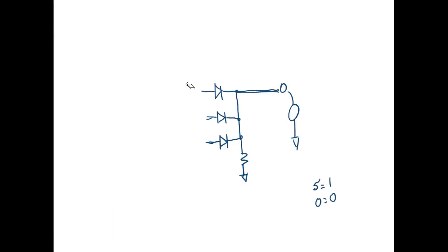So these guys have been around for years. And anybody says that they're not still used, that you don't understand digital, you'll run into these a lot because they're very simple. I can control how many inputs we have. So if I go out and buy a logic gate, you're gonna be set by the number of inputs inside that integrated circuit, right? You understand? If you wanted 15 inputs on this, you could use just 15 diodes. You can buy diodes, by the way, in integrated circuits. We'll talk about that.